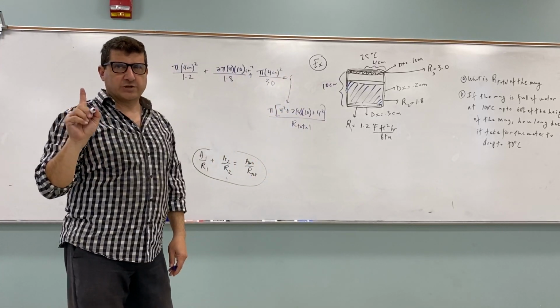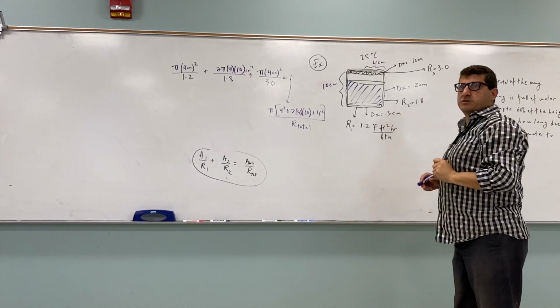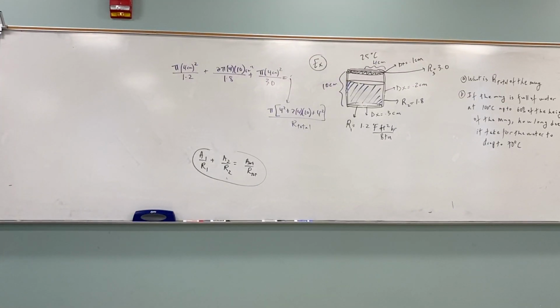But if we do this, we're making one mistake because we haven't included their thicknesses, right? The respective thicknesses. In this table that we saw, how are the R values given? R values for various materials normalized to a 1-inch thickness. In practice, the values will have been obtained using different methods and thicknesses. Typical values are approximations based on the average of available figures. The last column gives RSI values normalized to a meter thickness. So, in other words, these ones are per inch of the material, and these are per meter of the material.